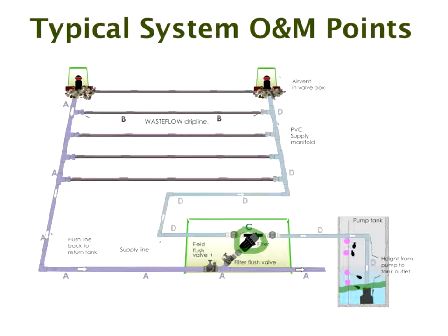Okay, then again, you've got your flush valves. Probably once a year it's frequent enough to take the flush valve apart and just check that there's no dirt under the rubber, and you've got both your flush valves.